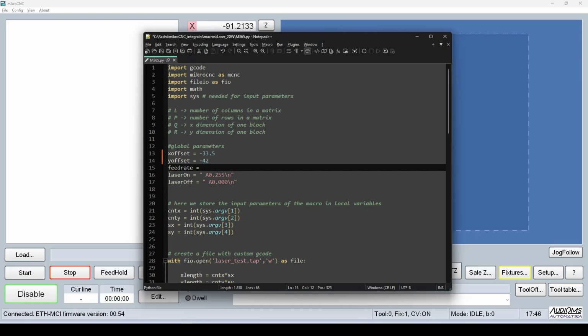The feed rate should not be too high, because then the laser can't penetrate the foam fully, and not too low, because then the work table will be damaged excessively. We experimented with a few different feed rates and found 700 to do just fine. We made it so that you can also adjust the power of the laser by changing this number right here.